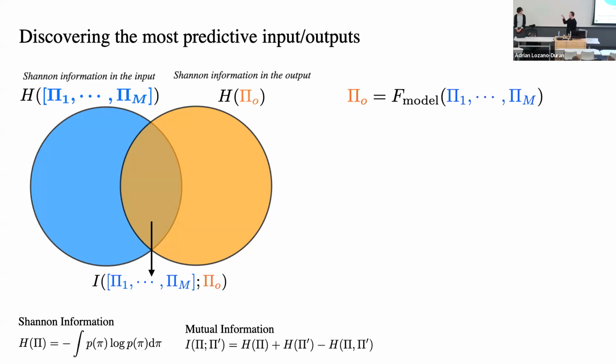And it's very important. If you don't do that, then the performance might drop a lot, because your model doesn't need to fit the data, it has to find how the solution scales with the dimensionless numbers that control the problem. And that's the key. And that's how the model can actually extrapolate a lot in dimensional space, but in dimensionless space, everything is very contained all the time. That's why the confidence in the aircraft was very high. You can say, how is that possible if the Reynolds number that you have there is much higher? Well, because I can rearrange my inputs and outputs in a dimensionless form that brings everything together to the same order of magnitude.